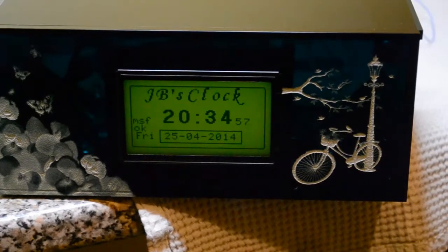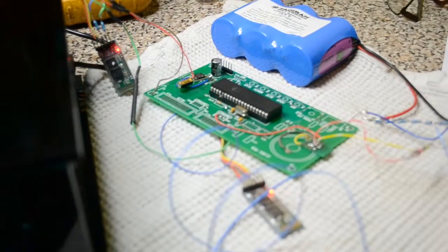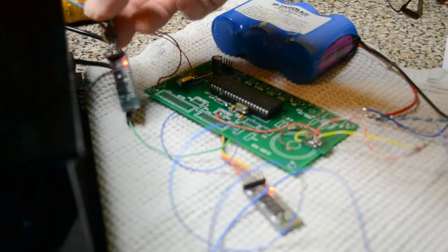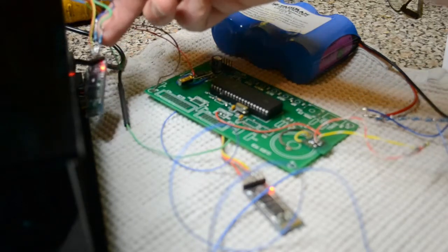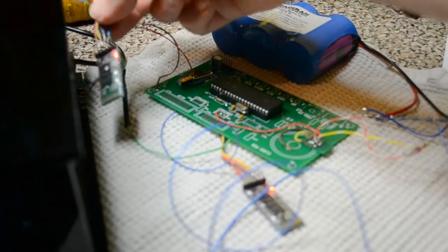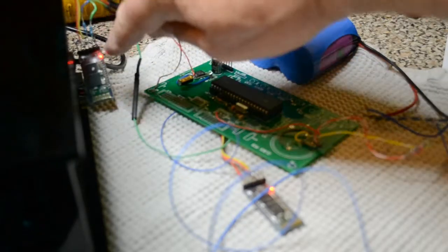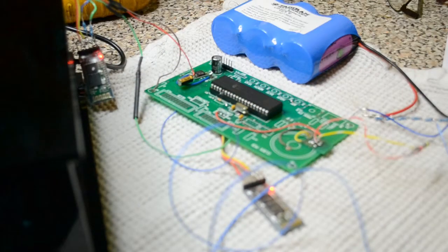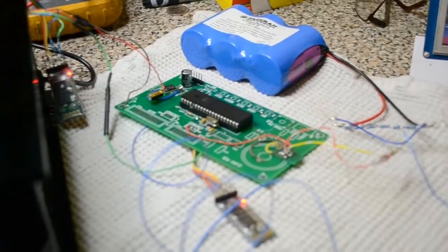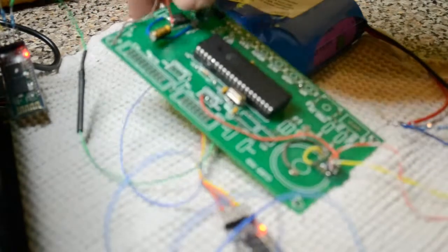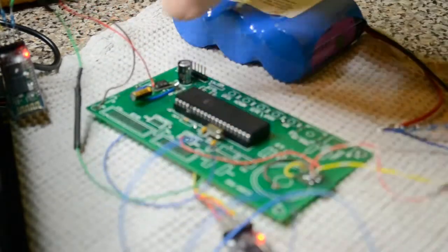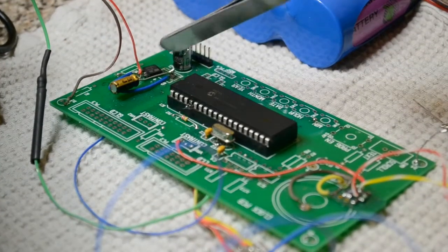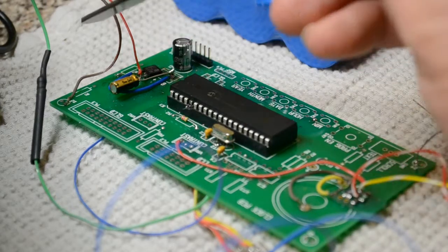So let me take you back to the circuit board. Right, this is the back of the clock. This is the simple UART transmitter, Bluetooth, transmitting my data. Just transmitting the time, nothing else, and that's running off my 5-volt PIC microcontroller clock. So I've got two resistors in line with the transmit and receive lines, and this board is an additional sort of clock PC, but I'm using it for the solar panel. I've just got simple power there, and in that bottom corner a 3.3 volt regulator with a decoupling capacitor, so that's power and ground.